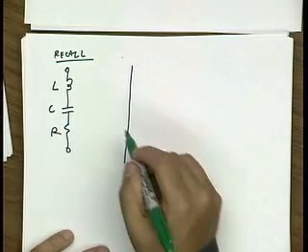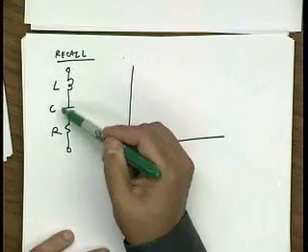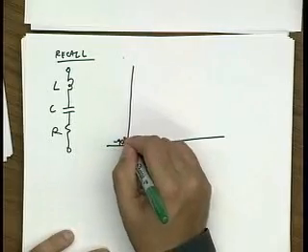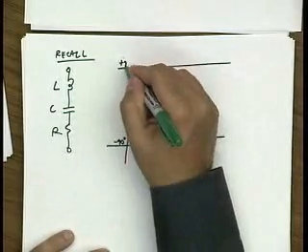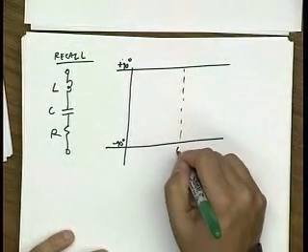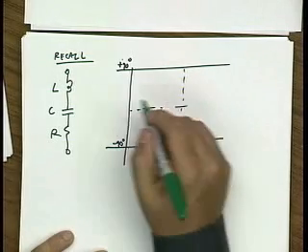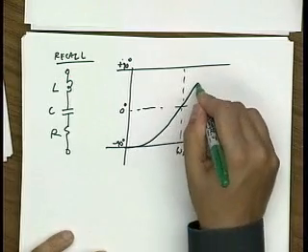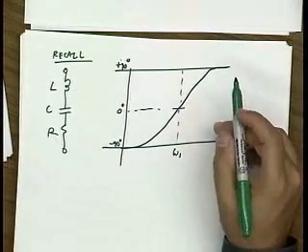We know that a series LCR circuit at very low frequencies just looks like a capacitor, so the phase shift would be minus 90 degrees. For really high frequencies, it looks like an inductor, so the phase shift would be 90 degrees. Exactly at resonance, the phase shift is 0 degrees. And it'll change smoothly from minus 90 degrees to plus 90 as we cross resonance.